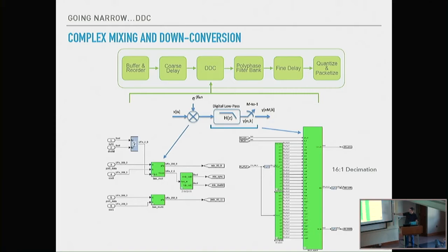So this is all wideband, wide concurrency that's taking place. The output of our DDC is very different. It is now effectively 1 sample as opposed to 8, and we're no longer working at the exact clock rate. Well, we're working at a still constant FPGA clock rate, clock tick, except the sample rate has dropped. We've got no gaps in our valid data because we are decimating, in this particular case, by 16.